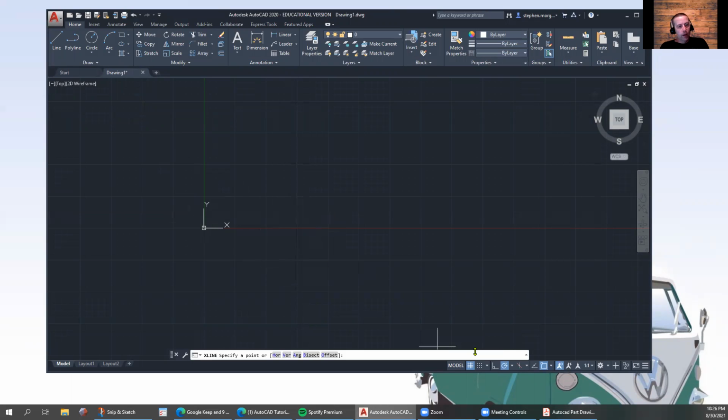And now here's where I like to toggle on the grid. Right now you're going to notice that I can't snap to my grid at all. My cursor's just floating and it's not locking in. But if I click this grid, snap grid, now it's going to snap to my origin. That's what I want. Except that I'm not on the right layer. So let's go ahead and make the construction layer active. And I do not have my construction line selected for some reason.